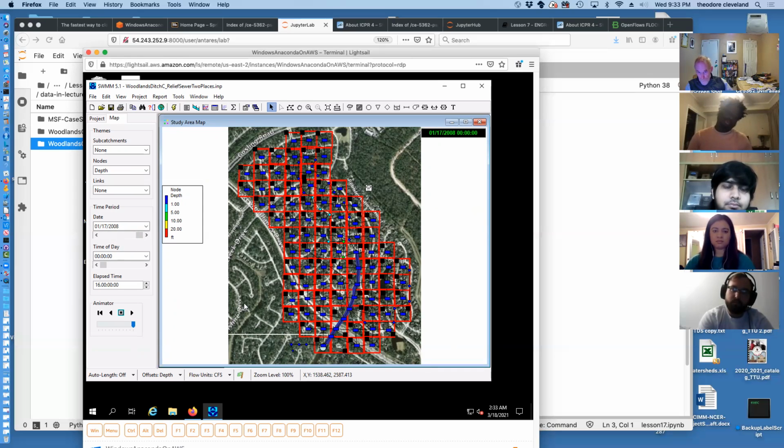Each of the black squares that are located mostly in the upper left-hand corner of each red square, but not in every single case, those are the drainage areas that happen to coincide physically with the same area as the storage cell. Each of the links is an overland flow link, either what we call a backyard or a street and ditch, or there's a few other geometries there.